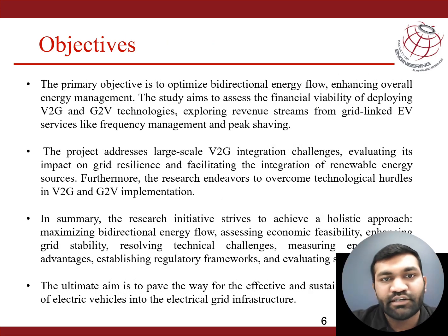The primary objective is to optimize bidirectional energy flow, enhancing overall energy management. The study aims to assess the financial viability of developing V2G and G2V technologies, exploring the revenue stream from the grid-linked electric vehicle service like frequency management and peak shaving. The project addressed large-scale V2G integration challenges, evaluating its impact on grid resilience and stability.